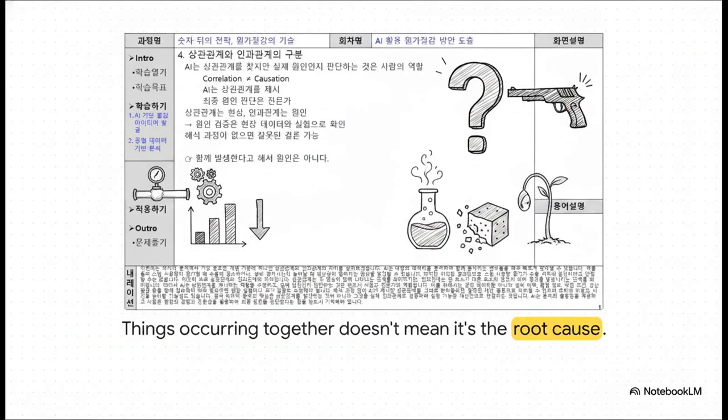Imagine this scenario out on the plant floor. If steam usage spikes right when your product yield drops, the AI is going to immediately flag that pattern. It looks like a smoking gun, right? But the engineer has to investigate the physical plant to prove it wasn't just some random coincidence. Maybe the steam usage spiked because of an entirely different process running nearby, and the yield dropped because a catalyst degraded. Just because they happen together absolutely doesn't mean one caused the other.